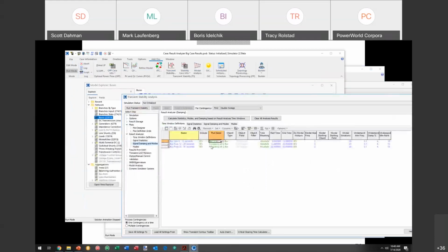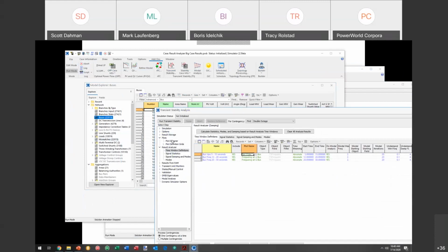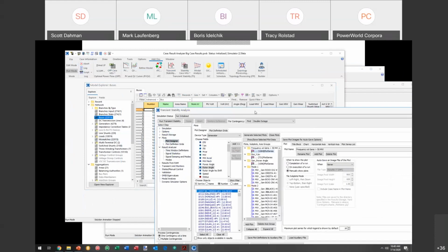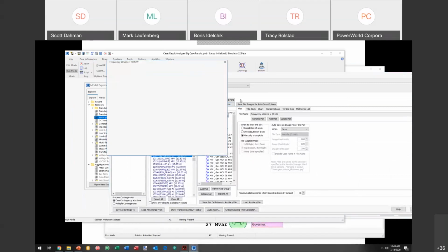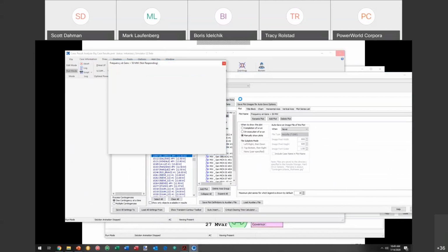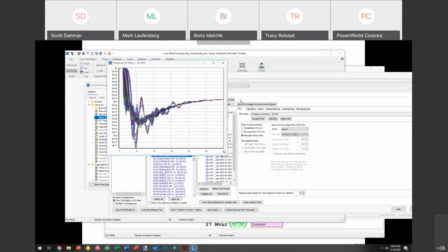All right, this case right here is a large WECC case with 22,000 buses in it. I've run a particular outage that we all run all the time to take 2 big generators out. If I look at the frequency results, here's a list of every generator that's above 50 megawatts, this is the frequency at those buses. Just pull that up. So that should be a familiar looking plot.